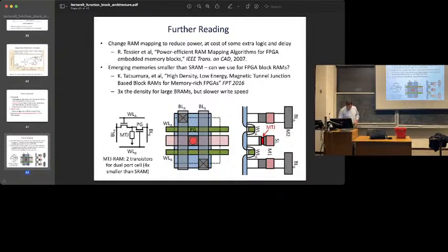But you'd have a slower write speed, which for FIFOs is probably going to be an issue. So I was involved in this paper. I think it's an interesting paper, and it talks a lot about the low-level circuitry of RAMs, if you're interested in that. Although ultimately I'd say the slower write speed means this is probably not a great idea to do. And there's another challenge, which is that FPGAs tend to be in advanced process nodes. So anything that you do that's not standard, you integrate some new memory technology and it needs a custom process, is also an issue because you want to be on the latest process, and usually anything that you change is going to inhibit that.